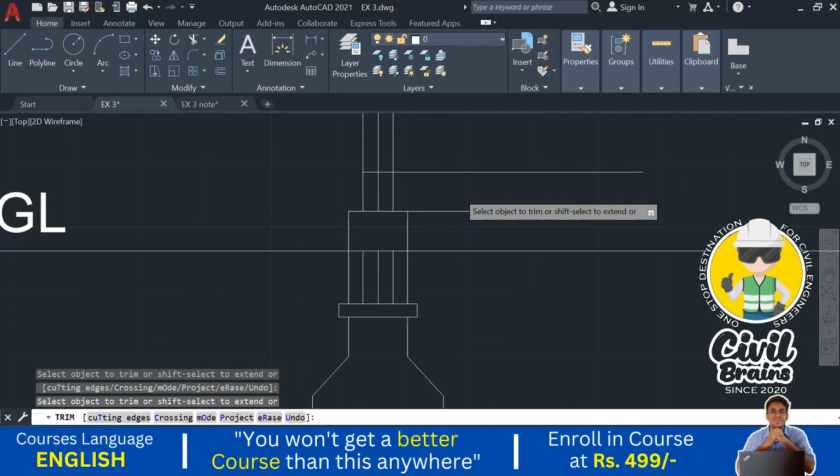So above the foundation, after the excavation, what is the next step? We need to provide the PCC. PCC of size 1:3, of thickness 0.1 meter. So offset, you just go to the offset, 0.1 meter of thickness.